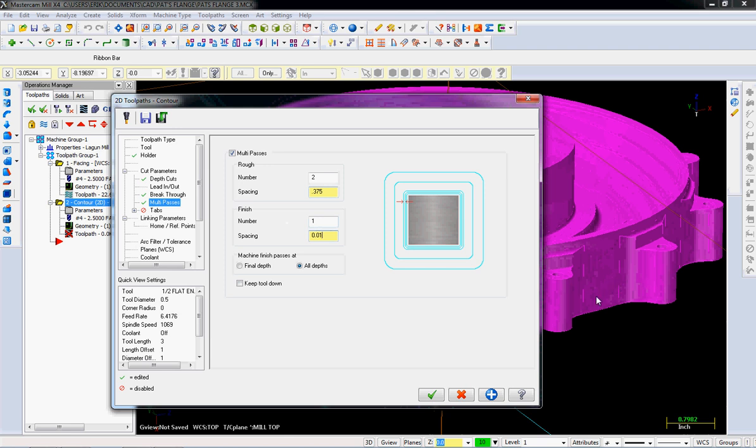So one extra pass 10 thou deep will make things nice and pretty. If you're having real good luck with your roughing pass with a high quality cutter, skip the finish pass. It'll make it faster. But finish passes are usually a pretty easy way to get nice finishes and get things accurate. It doesn't work in every case, but it works in lots of cases.